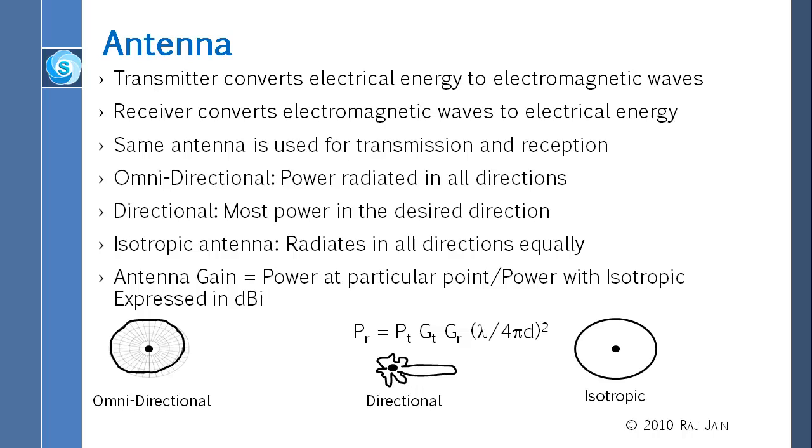But one thing you see from here, so there are several things on this slide. First thing you understand is directionality, right? Second thing you understand is that there are both transmitter and the receiver gains, right? Third thing is that the lambda makes a difference, the wavelength makes a difference. If you send a signal which has wavelength twice as much, you can get 4 times as much power at the same distance. Second thing is that the power goes down by the square of the distance.